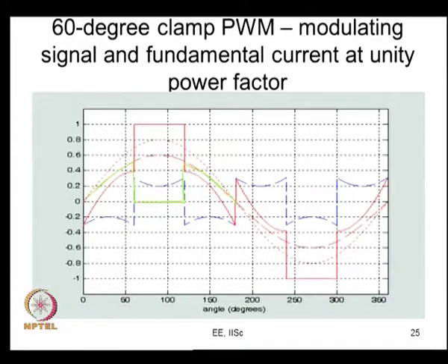The same thing you will have on the other side also, the switching energy loss here will be 0 and it will go like this, it will come down, then here again will go back to 0. This is how the switching energy loss will be. If you are considering the same carrier frequency as the conventional, then what happens? You actually save 50% of the switching loss.